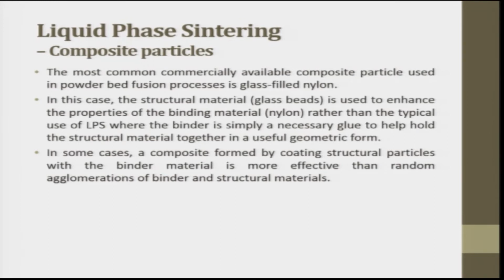The most common commercially available composite particles used in powder bed fusion process is glass filled nylon. In this case, the structural material glass beads is used to enhance the property of the binding material nylon, rather than the typical use of LPS, where the binder is simply a necessary glue to help hold the structural material together in a useful geometric form.